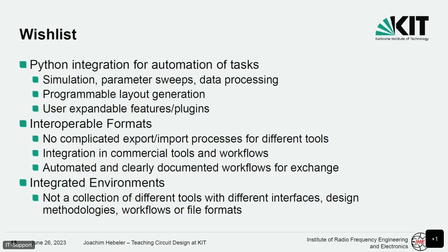Cadence and ADS do it very well with this interoperable format. You can just use the same layout in Cadence and in ADS. You don't have to change anything. That's a very big plus. You can take the same layout that you want to send to the fab, open it in ADS, open it in EMX, press simulate. You don't have to modify it. There is no error you can introduce. That's something important for us.